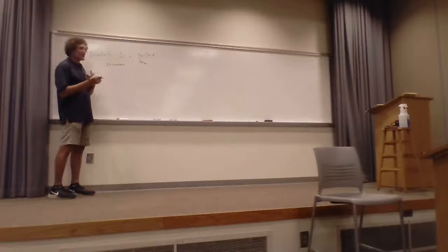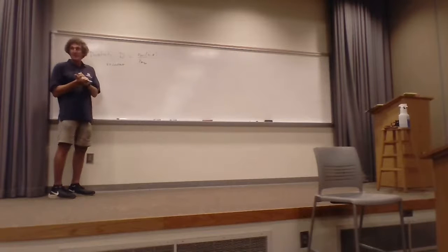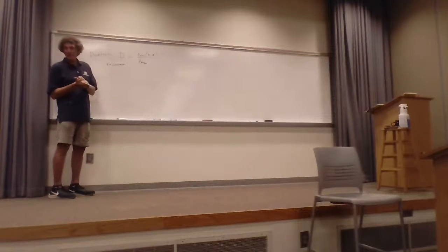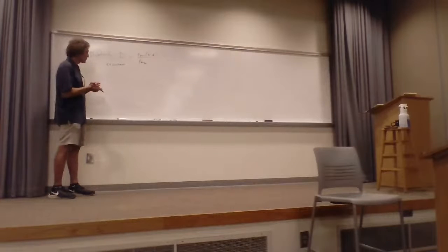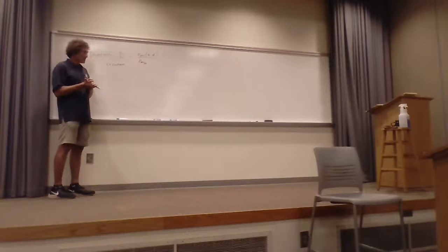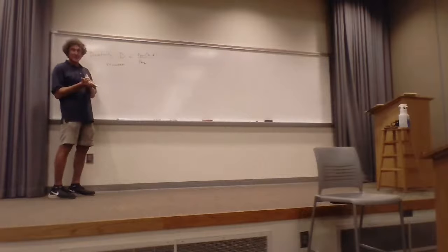I know that the power density for any antenna, in a lossless environment, or it makes no sense to talk about it, a pretty low loss environment, is equal to 1/2 E squared over eta. Well, if I think about the average power density, it's also going to have an E squared in it, right?